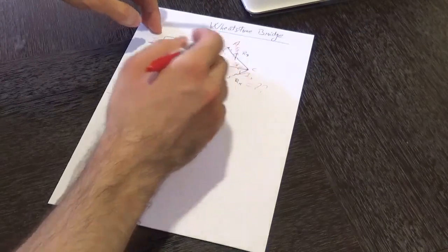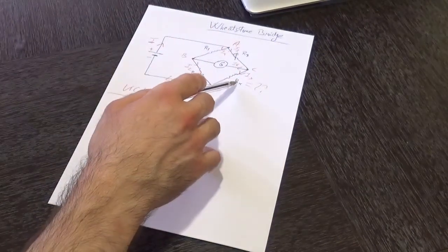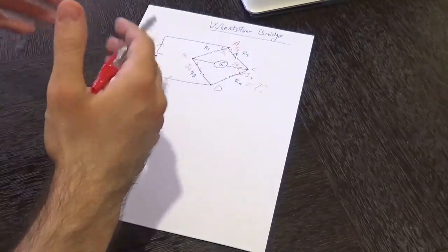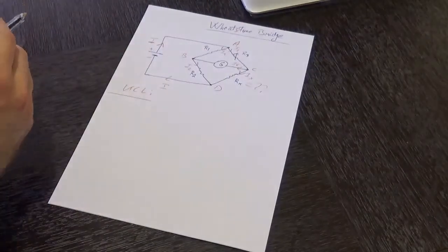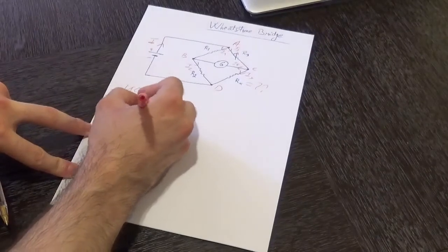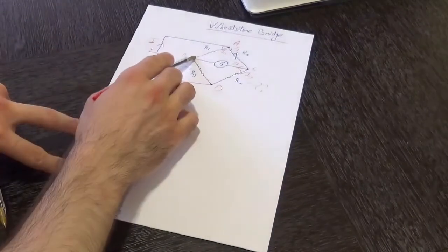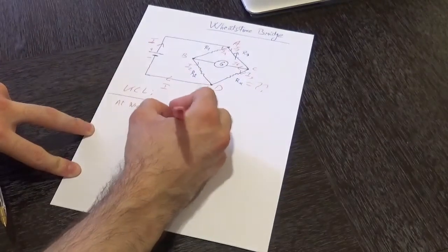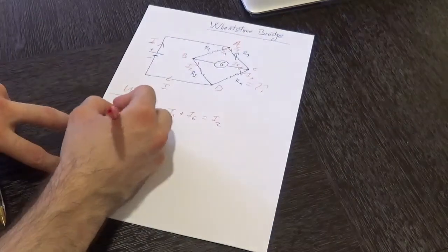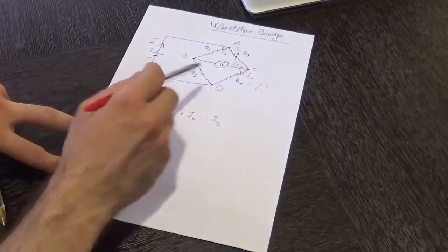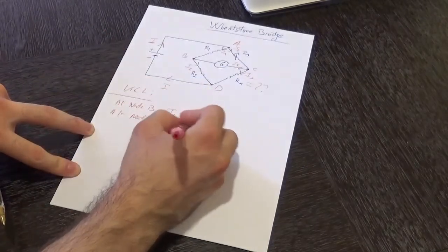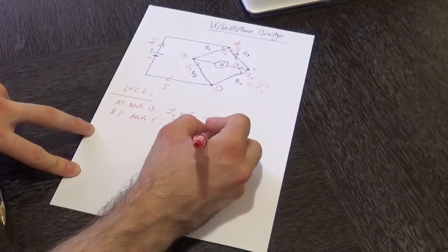As I have said before, our target is actually to establish an equation for our X. So first off, we need to establish two equations for the electrical currents, an equation at node B and another equation at node C. So at node B, we have I1 and IG coming into B, so I1 plus IG coming into B and giving out current I2. And then at node C, we have I3 coming into C and splitting into IG and IX. So I3 is equal to IG plus